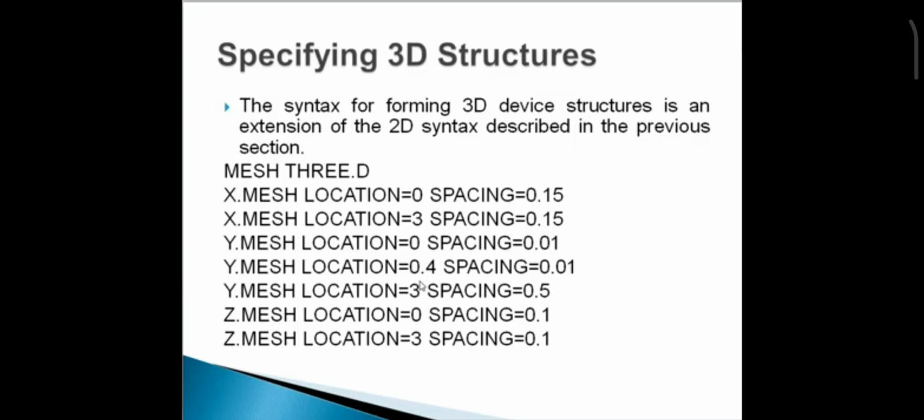Position parameters for the Z direction, Z minimum and Z maximum, are also used on the region, electrode and doping statements. Using the command language to define a structure, you can model a quasi 3D structure in Atlas 2D by specifying the cylindrical parameter on the mesh statement. There is one drawback: this structure has no dependence on the angle around the axis of rotation.